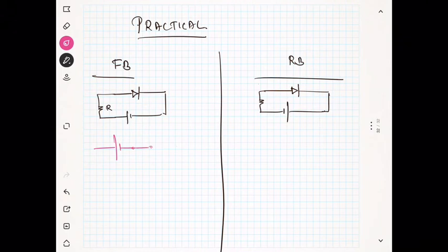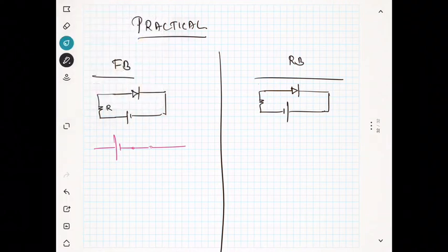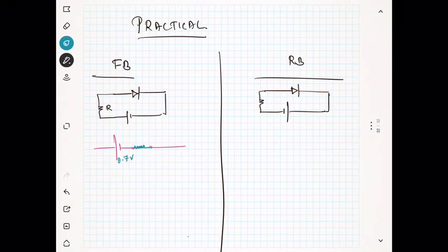Previously in the practical model I was using a short circuit, but it is not a short circuit only. You have some more things. You have the resistance of the diode. The diode will show a small resistance, because the diode is not perfect. The diode is having a resistance. So the diode is having 0.7 volt here. That means you can see a 0.7 volt source and a resistance RD dash. That's it. Now I can give an example here itself. Example, I will give it on the next page. Similarly, in the open circuit, in the reverse bias, you have the diode like this.